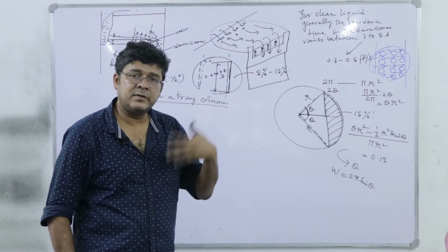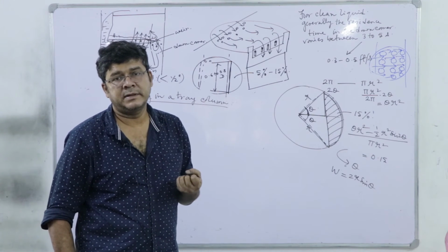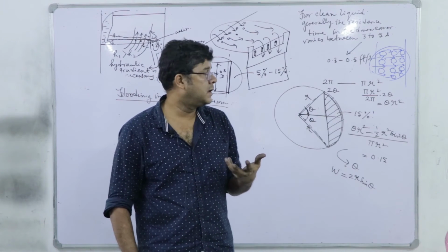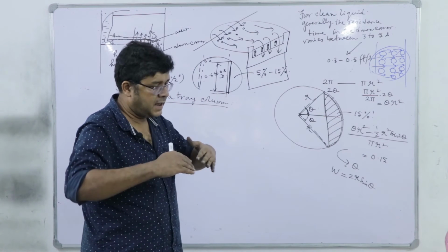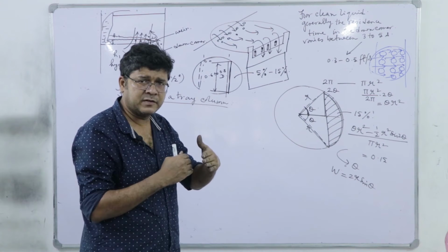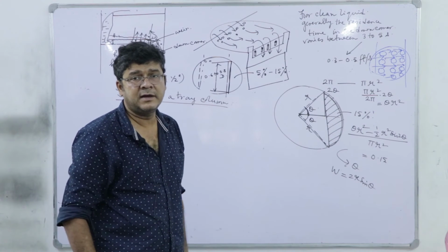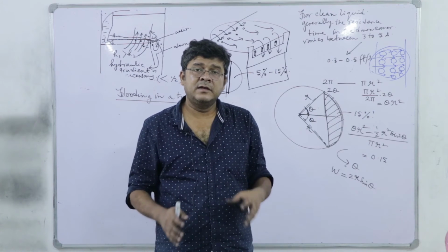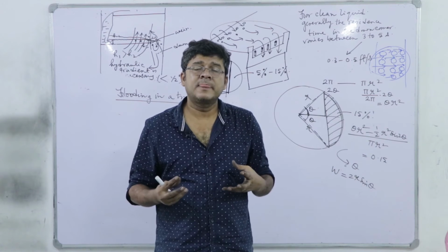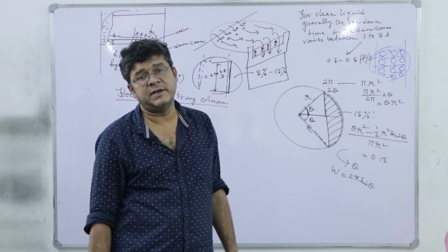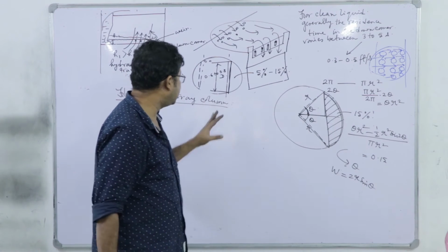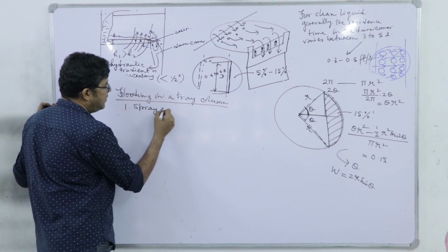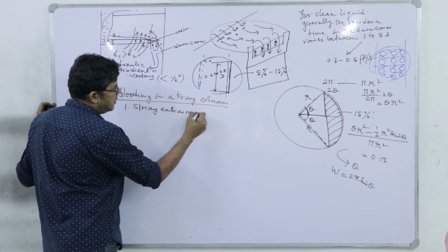And whenever the liquid starts accumulating, what will happen? Previously, the liquid was the continuous phase and the gas the dispersed phase, and there was a certain pressure drop because you were maintaining a definite hydraulic gradient and liquid pool depth over every tray. When the liquid starts accumulating, the liquid pool height over the tray increases, right, and the downcomer chokes. The gas pressure drop will tremendously increase, leading to non-ideality. So, what are the different types of flooding? The first one is called spray entrainment flooding.